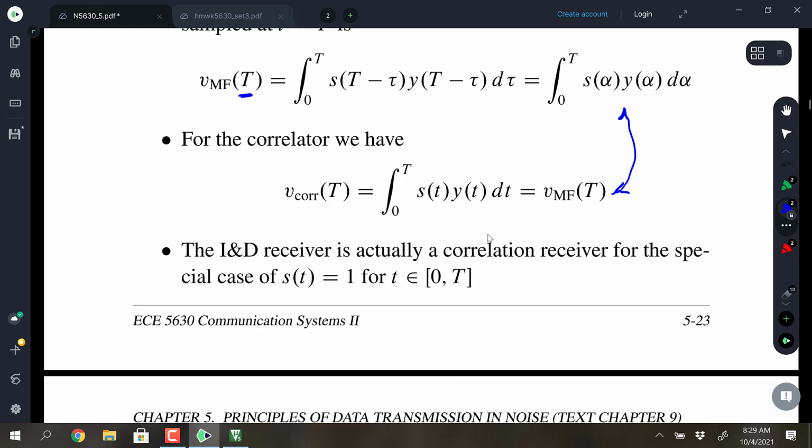Mathematically, it's considerably more satisfying to correlate our received signal with all the different signals we expect in our set of possible waveforms, take the output of a bank of M correlators, and apply the max operator. We take the maximum and say that was the one that must have been sent. And that makes sense, doesn't it?